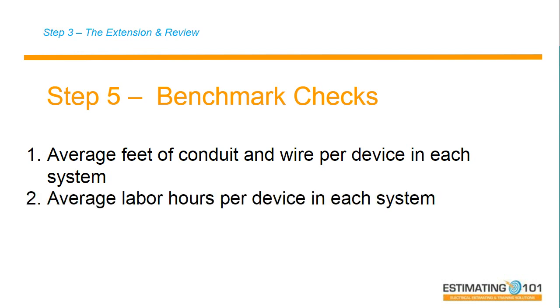I reviewed an estimate one time with a client. They had over 7 hours for every light fixture and occupancy sensor in a commercial building. It was way high. They had a serious error. This is a great way of checking your estimates. You'll do yourself a great favor of abandoning square foot analysis. You can use square foot analysis for budgeting, but the great key to reviewing an estimate, in my experience and professional opinion, is reviewing the average labor hours per device per system.